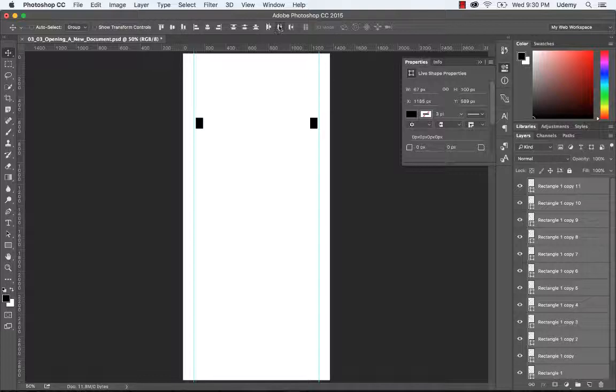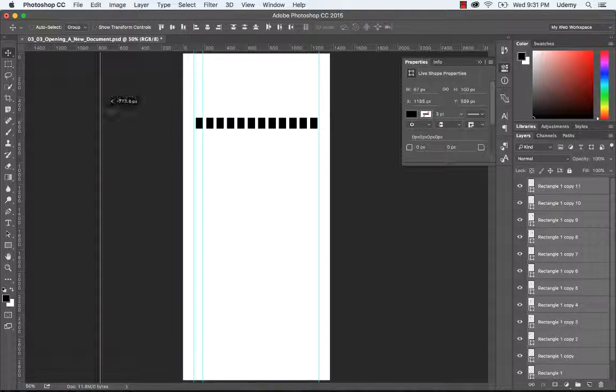And this little button right here called Distribute Horizontal Centers, that's what you want to click on, and then watch what happens to all of your layers. You've got perfect spaces, and these are perfect 30 pixel spaces in between the 67 pixel columns. So leave all these layers selected, and now it's just a matter of clicking and dragging guides out into each one of these little spaces.